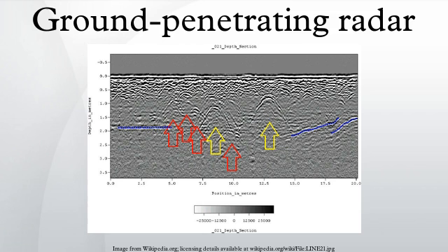Ground-penetrating radar is a geophysical method that uses radar pulses to image the subsurface. This non-destructive method uses electromagnetic radiation in the microwave band of the radio spectrum, and detects the reflected signals from subsurface structures. GPR can be used in a variety of media, including rock, soil, ice, fresh water, pavements and structures. It can detect objects, changes in material, and voids and cracks.